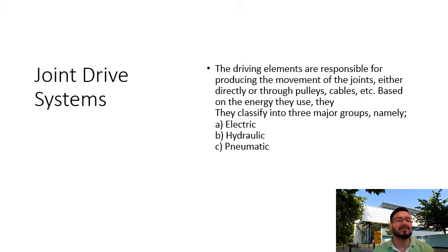Electric drive robots are relatively accurate compared with hydraulic powered robots. By contrast, hydraulic drive robots can be designed with greater lift capacity. The drive system, position sensors, and speed sensor if used, and feedback control systems for the joints determine the dynamic response characteristics of the manipulator.